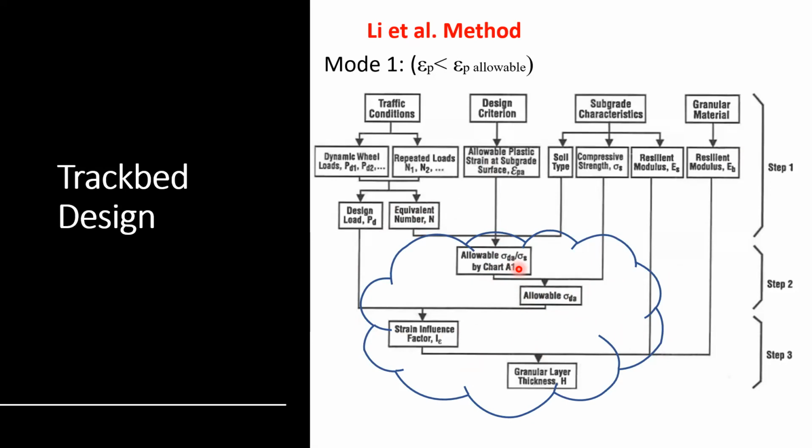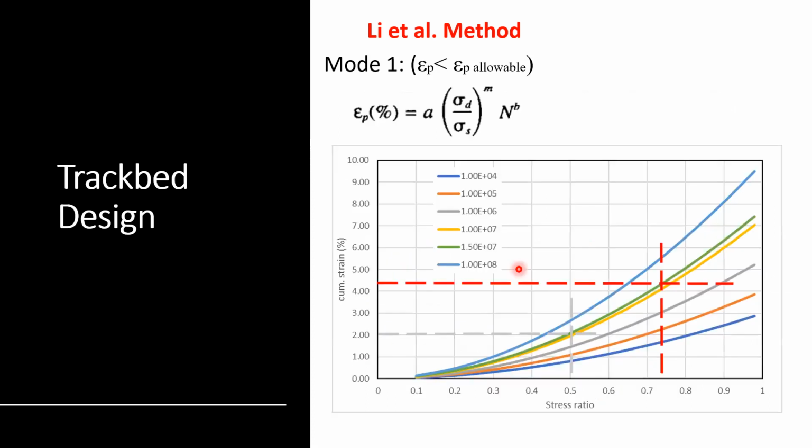So this is just an example I dug from one of my old projects. The equation they provided here correlates your plastic strain to the stress ratio. A, M, and B are your shear strength parameters. Lee et al. have done a lot of work as well, trying to specify guidance as to how to get the A, the M, the B from a quite intensive database.